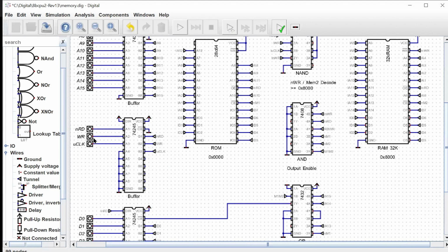I was using the same signal that the RAM chip write signal is using. I shouldn't have been using that. I should have just been using the simple write signal there. Okay, so that's our fix. We want to remove the read-write signal that was there before. We want to cut that signal and just wire that to ground. So let's take a look at what I decided to do.